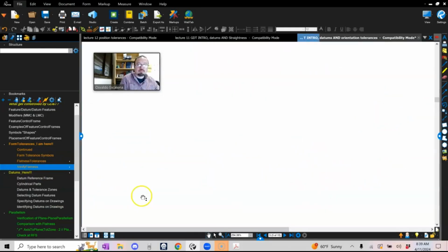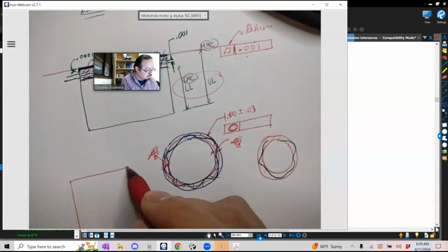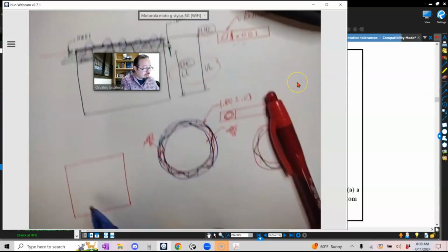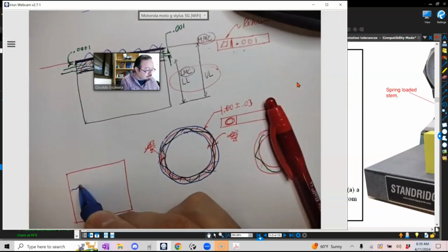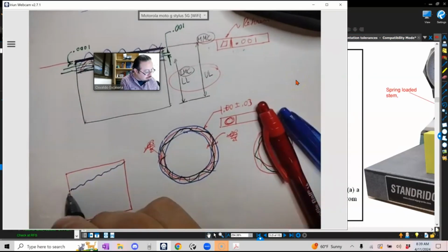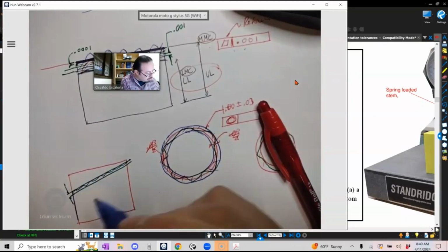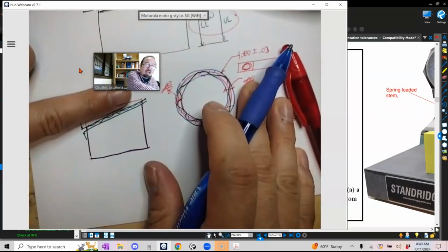Well, if you guys were to look at flatness, the only thing that I'm controlling is the surface of it. And again, the surface in terms of form. So my part could be as twisted as this, as long as my tolerance zone of flatness, again, these are the parallel planes, 0.003. That means when my part came, here is this blue part, right? I just make sure that the surface that I'm calling flatness. And again, the red will not exist because this is how my part came, right?